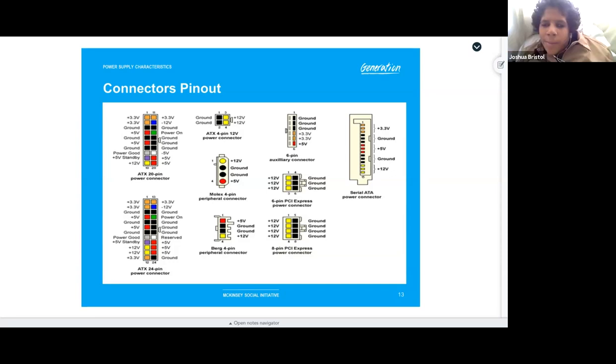I noticed something. There's one extra ground in the ATX 24 pin on the bottom right. Then on the 20, that only has plus 5 volts on the bottom right. Well, no, otherwise they're identical, remember. These two cables are identical with the exception that they added these four on the bottom. If we look at it, they both start with 3 oranges with a blue, sets of black.